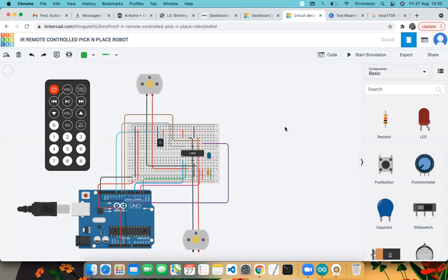Normally the telephone or mobile phone bandwidth for any permissible audio frequency is 300 hertz to 3.4 kilohertz, so a bandwidth of 3 kilohertz. Fine. So channel 1 in FM is providing a program in which somebody is talking, or maybe singing or stuff like that.